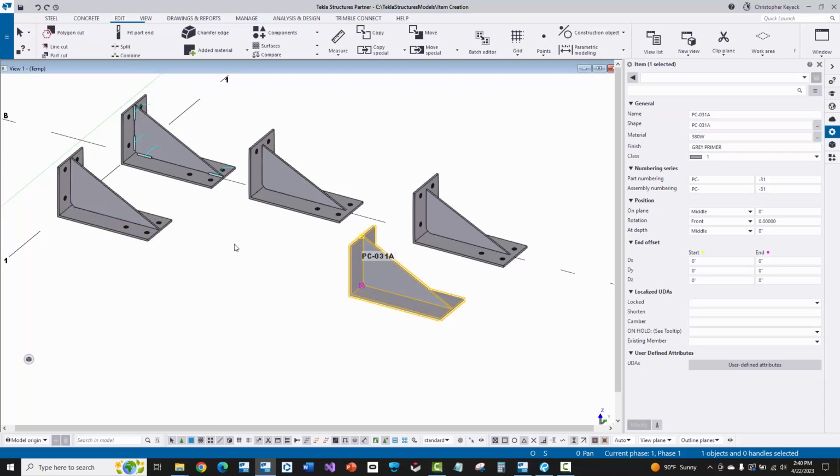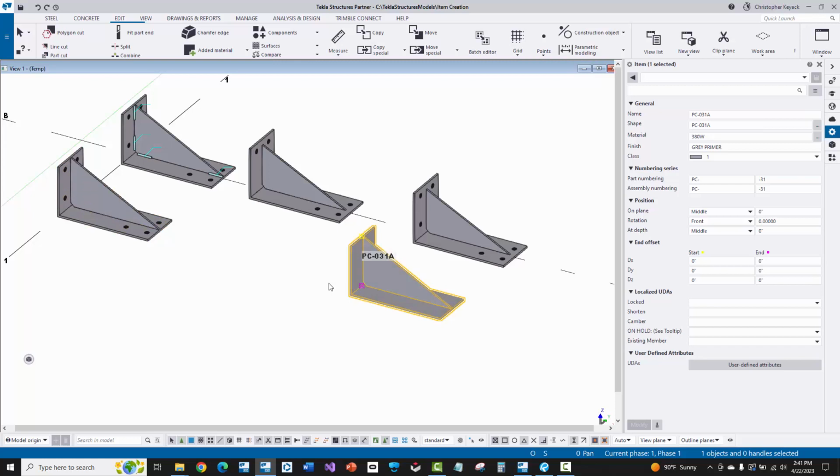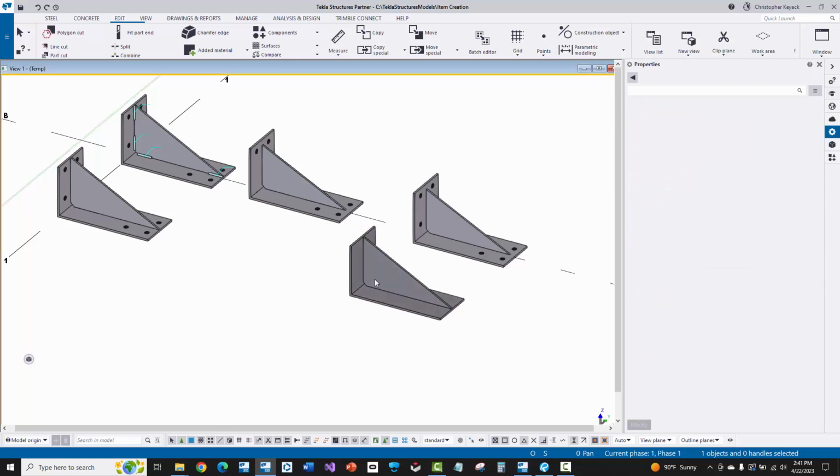So that's something important for you to know. If you use any modeling objects in Tekla to then convert into a shape, the first item of your part that you attached to, so I attached the stiffener to the polybeam, so that was kind of like the driving part of my attached or fused material. Whatever the coordinate system is of that part, like the input points, that's going to drive the coordinate system of your shape geometry when you convert it to an item, just like I did here. Now, it's not a super big deal. I don't know of any way to change it, but I'm actually going to be able to work around that here in a second. But I did want to explain how these 2 points got picked by Tekla to put the shape in. Now watch this.